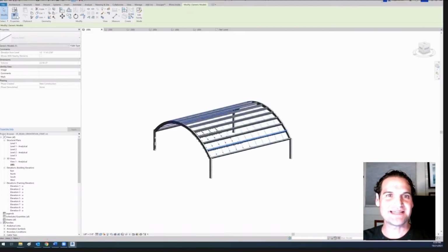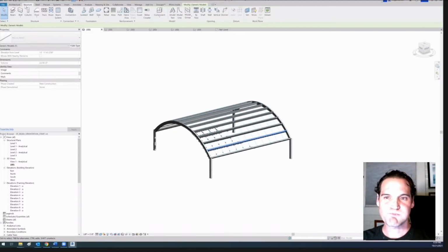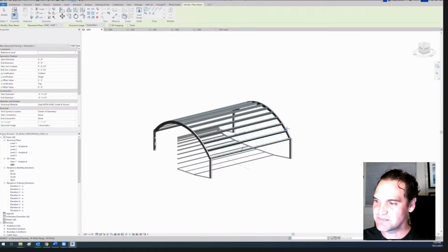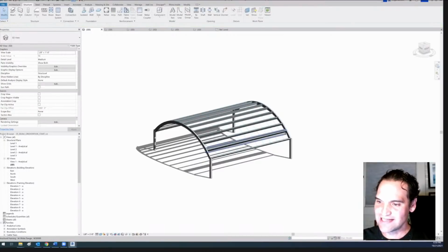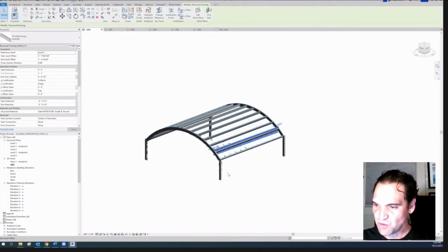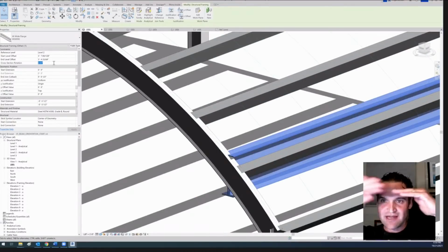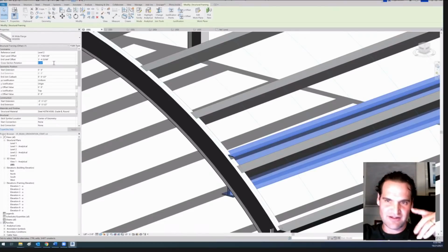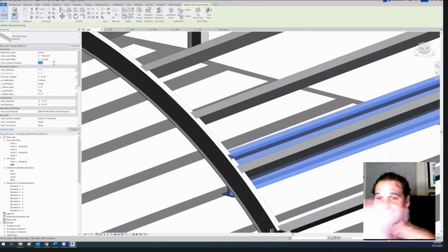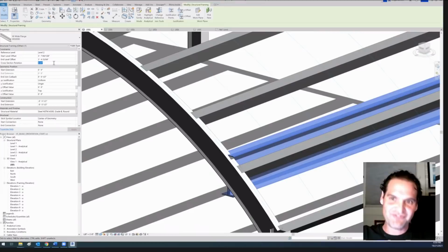So basically the way it works, and it's not in the book. I plan to do a volume 2 on it, which is you basically, when you place the structural beam, then Dynamo will analyze the surface. And then it will go in and modify the cross-section rotation based on tangent vectors, normal vectors to a plane tangent to where that flange is ideally supposed to be. And then it will rotate it into place. So that's how I kind of do it now.